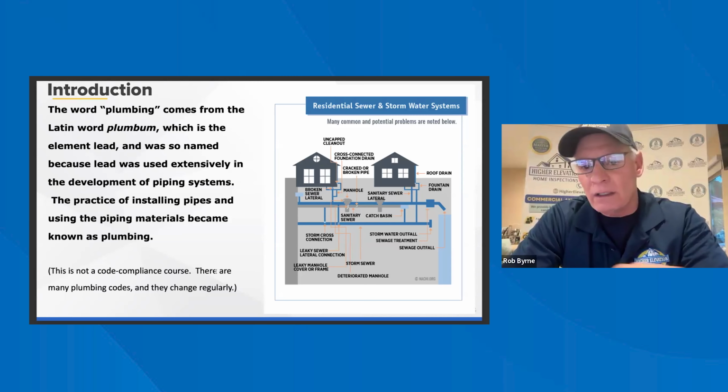Water pressure defects. In order to get the most meaningful results when inspecting the water pressure, it is good practice to inspect the plumbing fixtures at the highest point, correct? So second floor, third floor, wherever you're going, you'll see a change in pressure. Back to this again. I guess this is important. We're at it again. We talked about the 1/2 inch and the 3/4, and how that would change the flow.